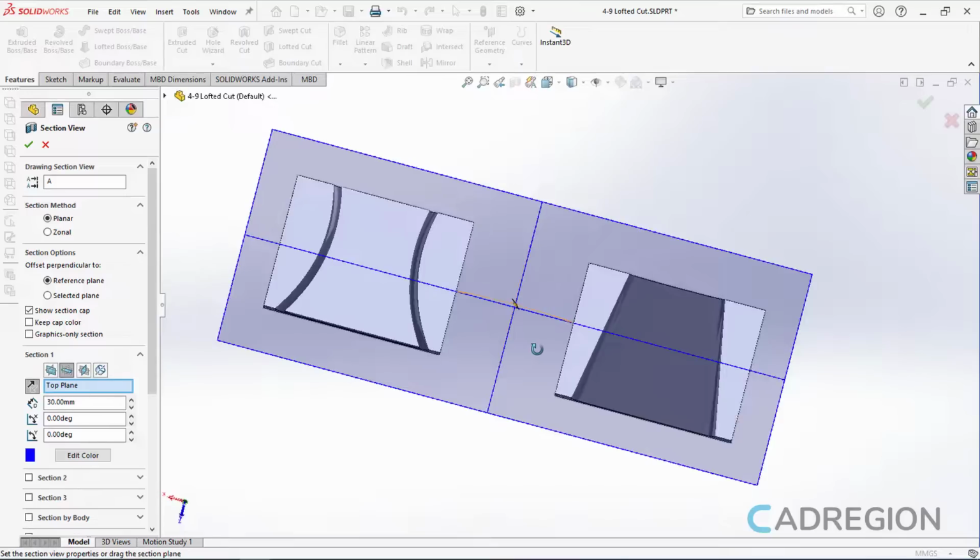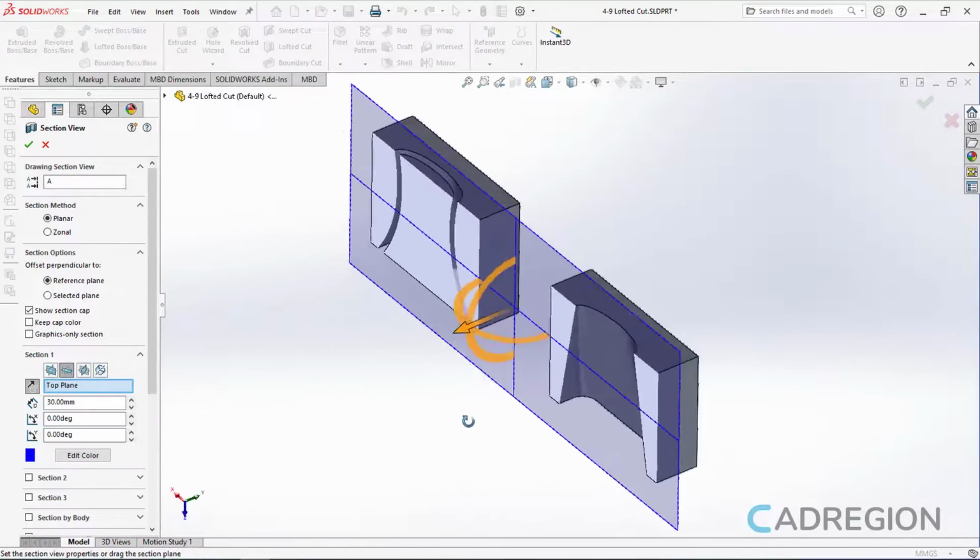Before we finish the lesson, I should mention that if you activate the Thin Feature option while you create the Lofted Cut extrusion, you cannot deactivate this option when you edit the feature. Now you can use this tool too to remove material from your own 3D objects.